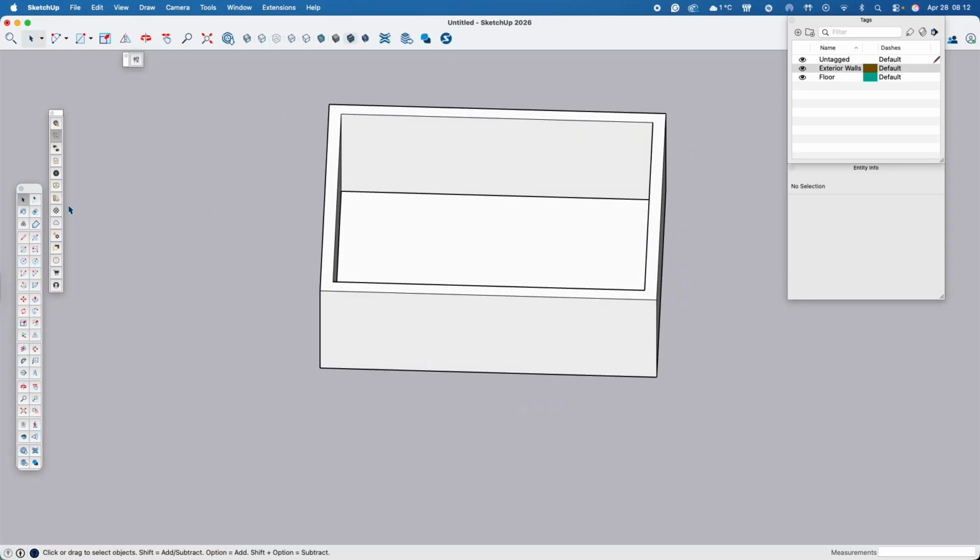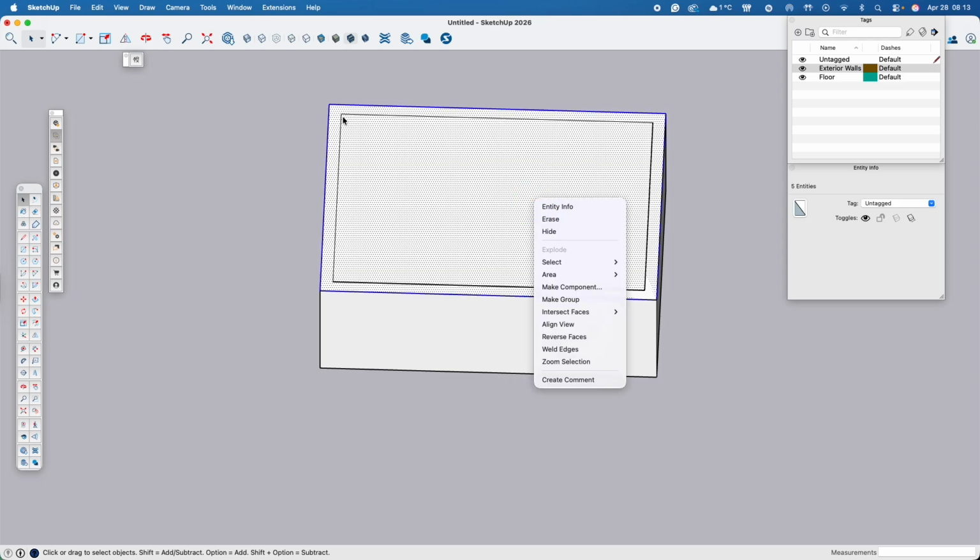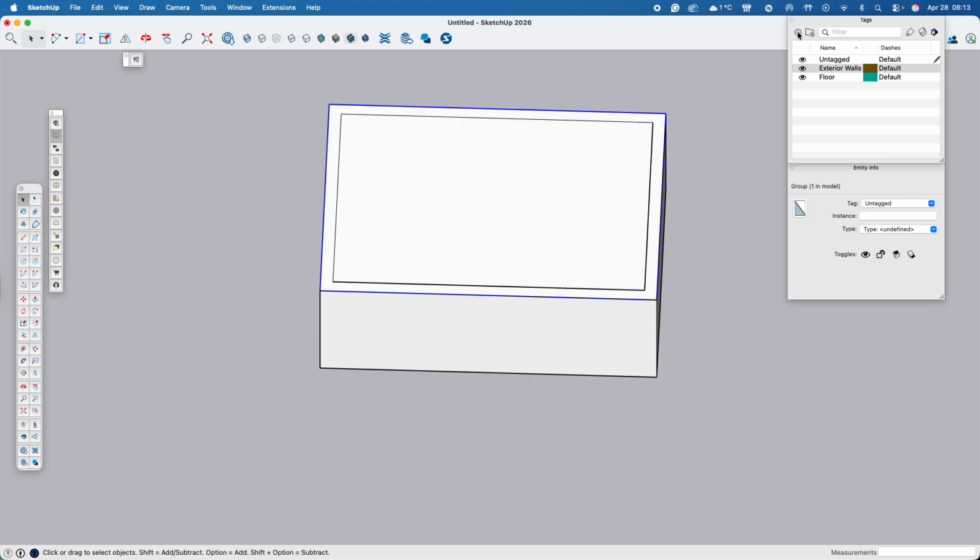Okay, I am going to draw a rectangle. So you go here, or R on your keyboard, and then I'll go to my endpoint. It will stick by itself. So endpoint in the group, then same thing here, and click a second time. Then I am going right away to group that rectangle. So triple click, it gets blued, make a group, and then I'm going to tag it. So tag roof, enter.